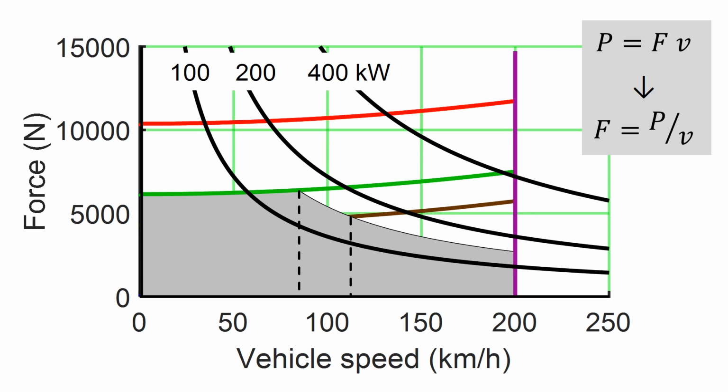To accept that the vehicle cannot drive uphill a steep gradient at high speed is usually not a problem, since the speed limit is reduced on roads with high gradients. To reduce the requirement for acceleration at high speed is probably the compromise which is the most noticeable for the driver, since acceleration on motorways often occurs. However, the 150 kilowatt traction power assumed allows this car to accelerate 3 meters per second square at 110 kilometers per hour, which should be considered as quite a good performance.